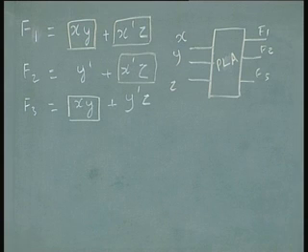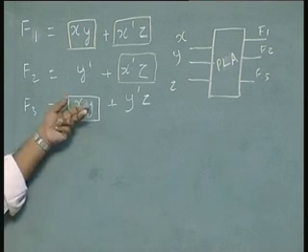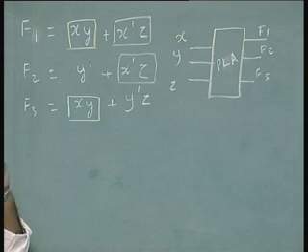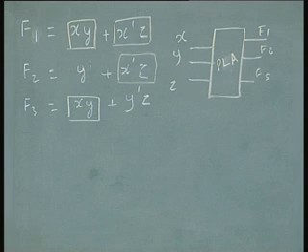How did I get it? In this case, as I said, the function was given to me. It could have been simplified, or sometimes you may have to be careful in simplifying it yourself. You do not oversimplify. Sometimes in a Karnaugh map approach, the traditional approach is to simplify to the minimum possible form. I would minimize such that I use the minimum number of AND gates, the minimum number of OR gates and the minimum number of inverters.